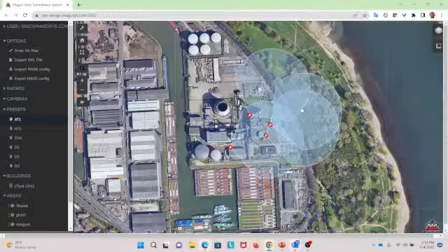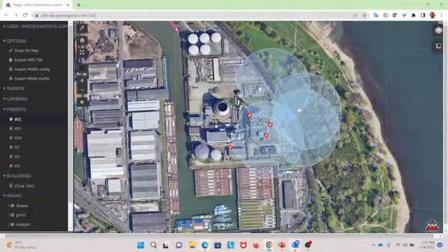This is a function sometimes very helpful during a design. Once you define the home position by finding your place, you can either type a city name as example, or you type a full address, or you type the latitude longitude, so the GPS data, jumping to whatever position.